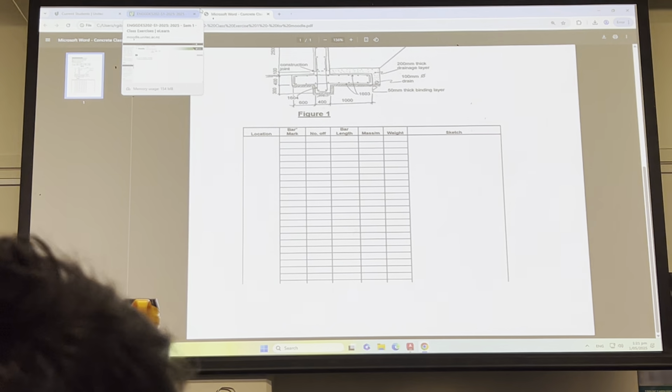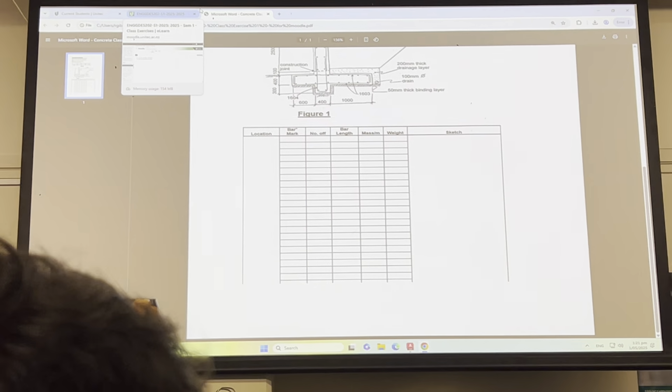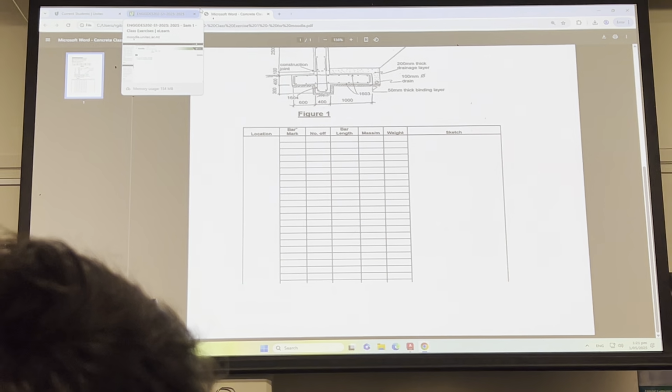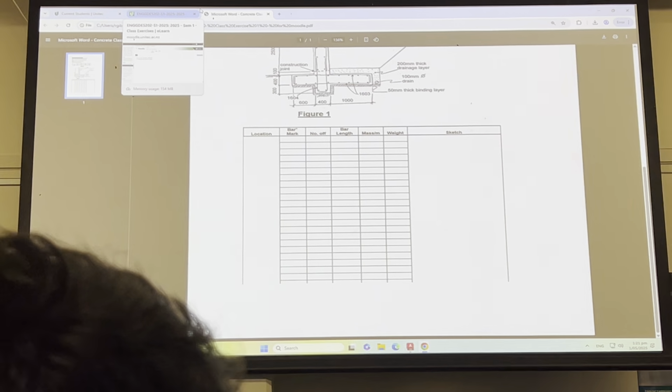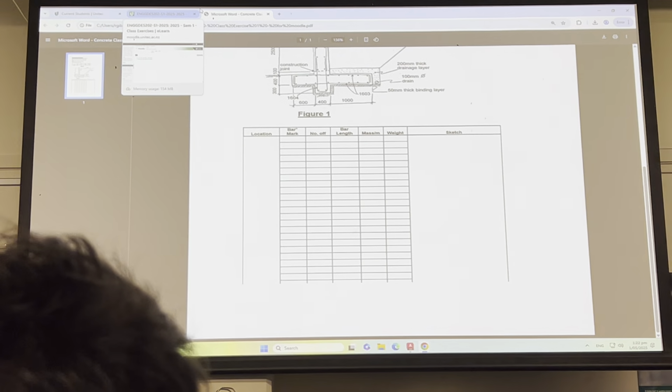It's exactly right, and it's how we price the reinforcing. There'll be a price per weight, per kilogram of the reinforcing, and as engineers we need to know a rough idea of the job and the cost. So you'll end up having to get a total weight, and then you can apply that to a cost overall. Of course, there's also labour, which has to factor into everything as well.